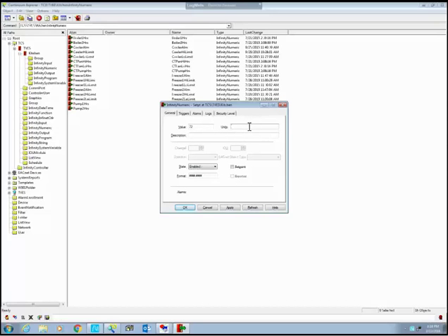If you want to set the units to degree F, you can type in degree F, which will show up. I usually like to hold down the Alt key and type 0176. That puts the degree sign there. It's kind of shorter, less clutter on the graphic. That is Alt 0176 while holding down the Alt key. That's an ASCII code if you want to look that up. You can put the description.